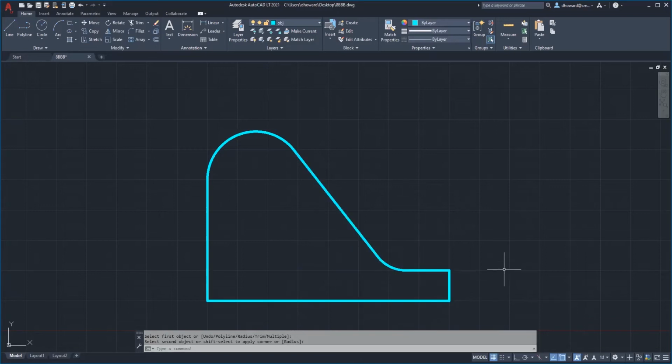And honestly, I think that's pretty good. I think that's about right. So I'm going to do that one more time. I'm going to hit undo. And the way you use the fillet command is you click on fillet right up there. And before you do anything, you have to type R, enter, and give it a value because it doesn't know how big a radius you want. I'll pick a bigger one this time. I'll say like 10. Let's see what happens when I put in 10.